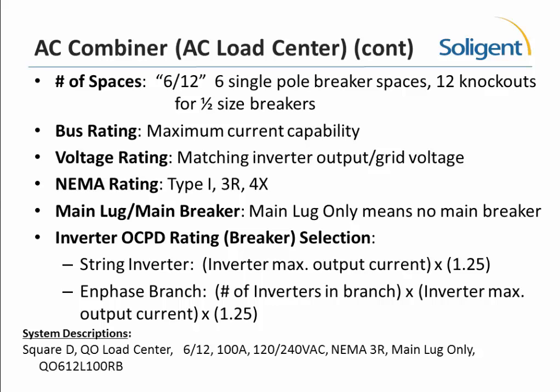What is the NEMA rating of the box? A type 1 is an indoor rated box. Can't be outside. It's got to be enclosed somewhere like in a garage or someplace. A 3R is good for outdoor, or a 4X, which can be mounted horizontally.